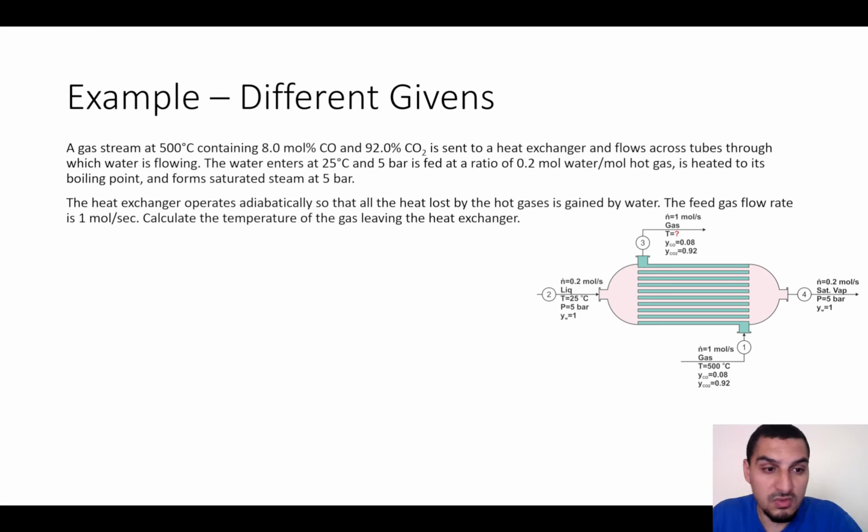The second point, which is a very important point, is that we said before that we are dealing with single phase problems. We haven't dealt with any enthalpy change due to phase change up till now. But what you see here is the water enters as liquid at 25 degrees Celsius and 5 bars, and exits as saturated vapor. So this water is changing its phase. It starts as liquid and ends as vapor. So there is a phase change here, and we said that at this point we deal with single phase systems.